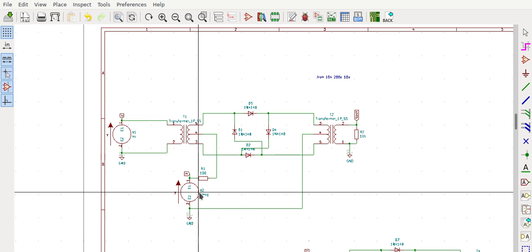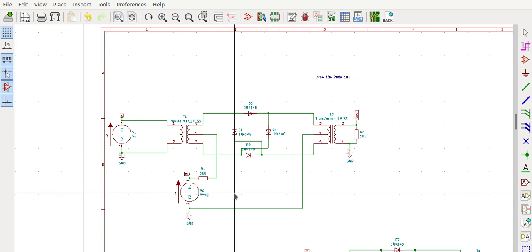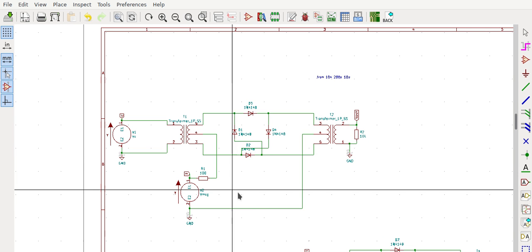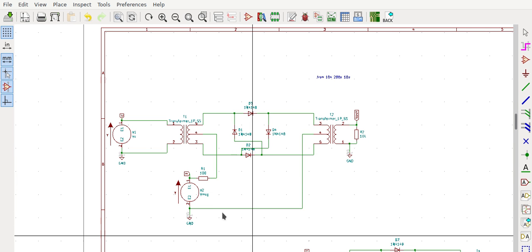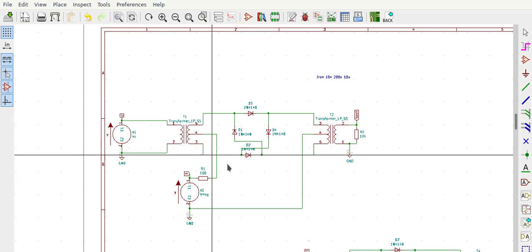So when it is positive 1 volts, you are multiplying it with positive 1 volts, the carrier, and when it is -1 volts, you are just inverting this signal stream. So you are multiplying this voltage with this voltage. That's all that this circuit is doing.